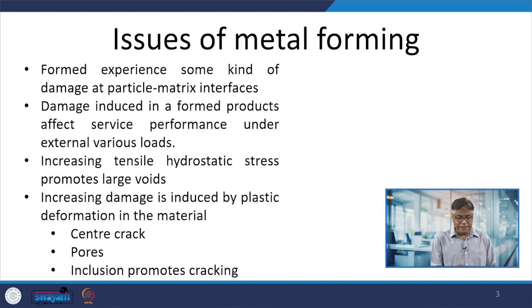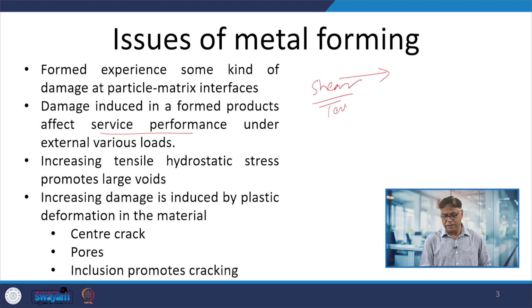This damage induced in these formed products affects the service performance under a variety of load conditions, especially under shear and tensile loading conditions in the presence of these voids. Under these kinds of stresses and loading, voids nucleated during the forming tend to grow and eventually their coalescence leads to the fracture.